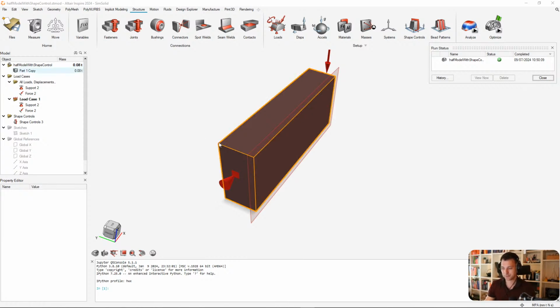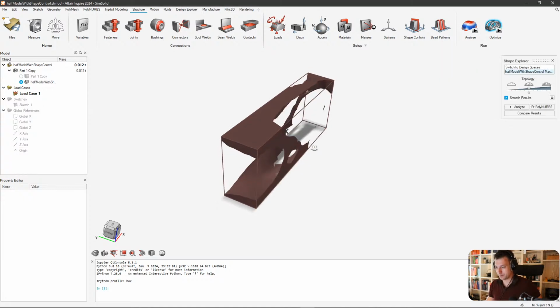If you would have this shape control plane in the middle, you perfectly can say, all right, do your optimization, and then the symmetry constraint is like this. I just go and cut with the symmetry plane and just match the densities so that they will be symmetric. And you will get a symmetric design which is symmetric regarding the symmetry plane you introduced. There are no additional constraints there, but design or density matching. That's my guess. And that's why this will differ.